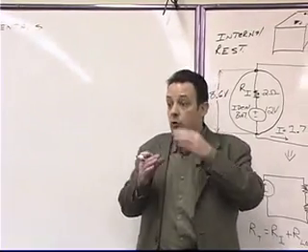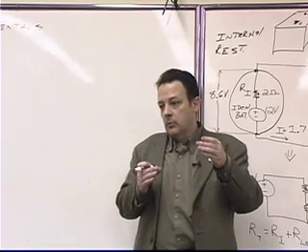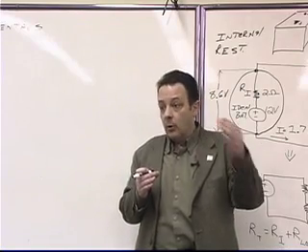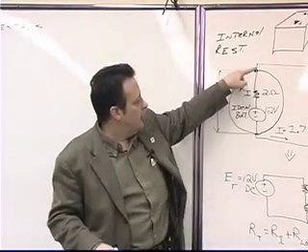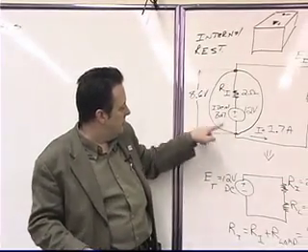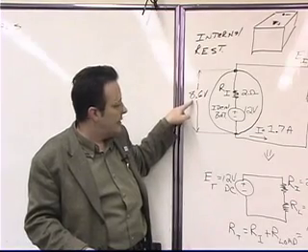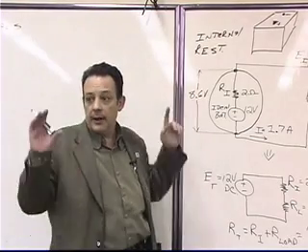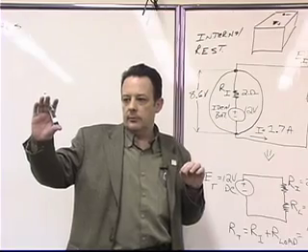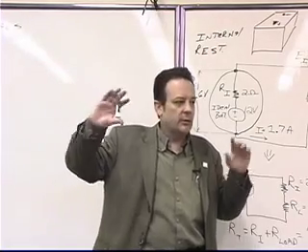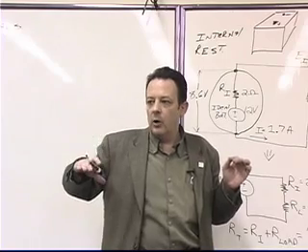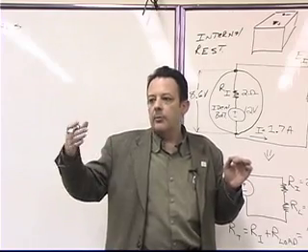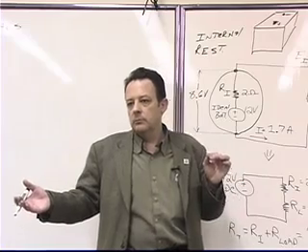You're going to have 2 batteries in parallel, or 3 batteries in parallel, or 4 batteries in parallel. Why is that? The reason is because your usable voltage, which is the voltage that actually appears on your amplifiers that are driving your radio system, is dropping down to a value that's lower than it can operate normally at. Okay?